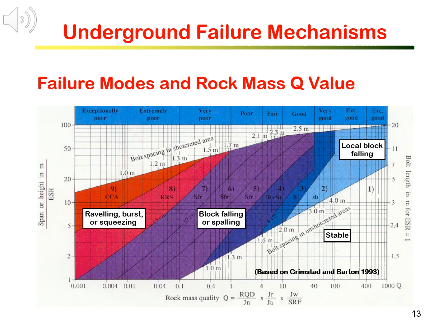The relationship between failure mode and rock mass quality can be found in support design. For example, in the Q-based design chart here, we note zones 2 and 3 are bolting for block failure and sliding. In zones 8 and 9, steel ribs and cast concrete lining are for general failure and squeezing.